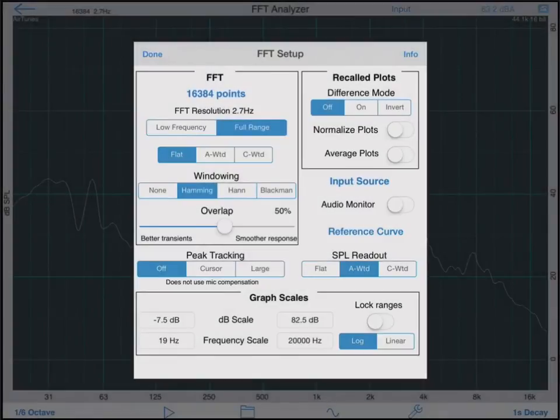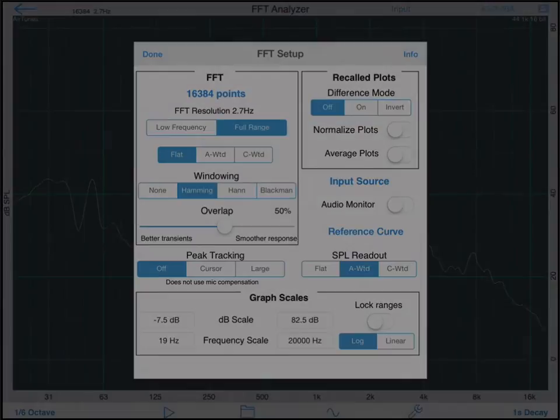There are options available for customizing the analysis with the windowing settings. Windowing accounts for the fact that each FFT sample is made up of a finite amount of points. Whenever we measure a non-periodic signal, the on and off ramps of the sample cause spectral splatter. In the FFT setup menu, you are able to pick 3 of the most widely used window functions, which multiply the signal by a tapering function to reduce this leakage.